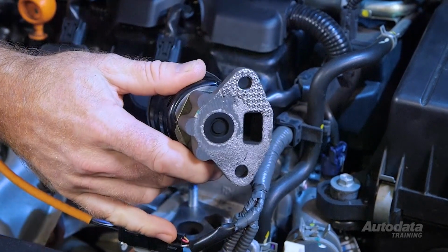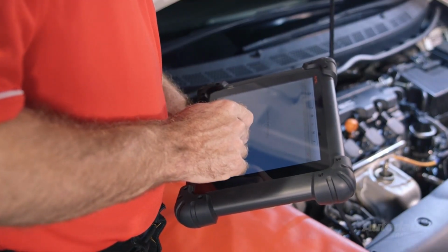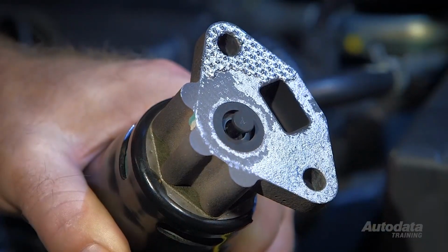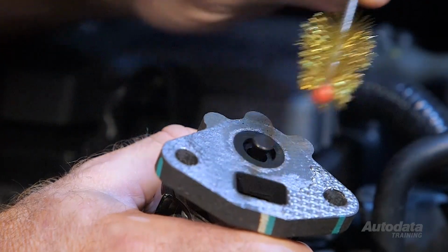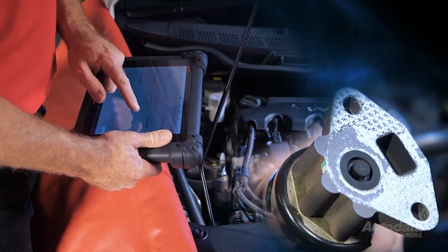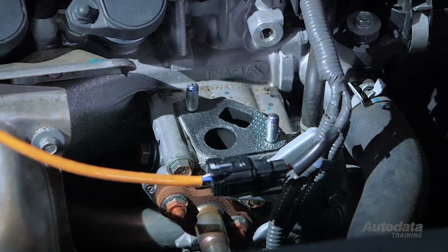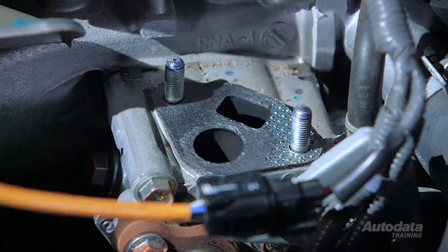You'll need to remove the valve for a visual inspection. Leave the valve plugged into the harness and use the scan tool to command the valve open and closed. You should see the pintle move as commanded. If the valve does not move, inspect for any carbon build-up that's preventing the pintle from opening or closing. Cleaning the EGR valve is acceptable as long as the solenoid is not subjected to any fluids. Retest the valve for free movement and smooth action. If the valve does not respond, then it will need replacing. If the pintle moved freely, then check the ports for any blockages.